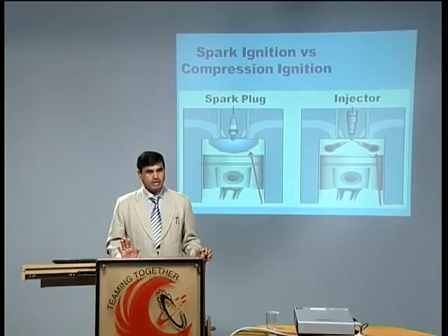When we have an 80 to 1 ratio, it is the idling condition, when there is no load, just like when we are waiting at a red light, the engine is just in start condition, and the amount of fuel injected into the cylinder is very small. That situation is termed as the idling situation. The fuel supplied to the cylinder is just keeping the piston and the crankshaft in moving condition, but no power is transferred to the wheels, it is just standing.